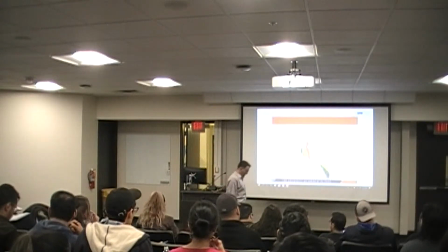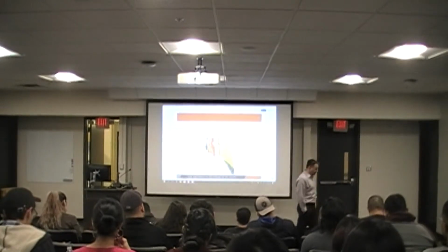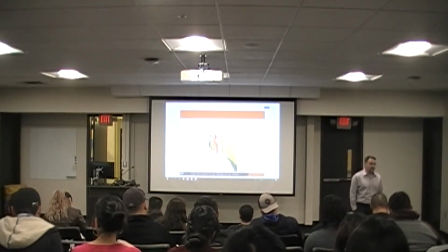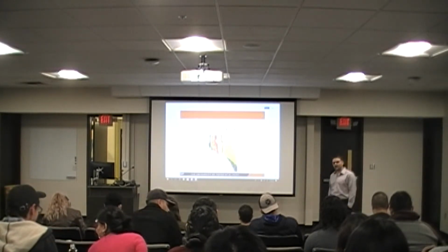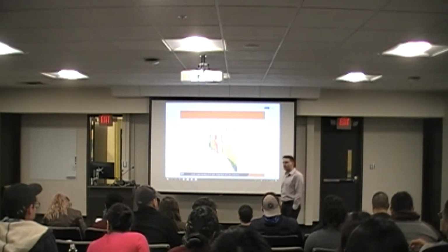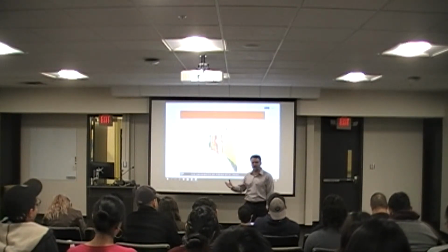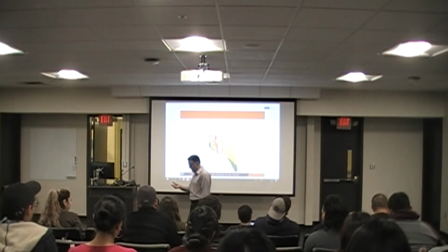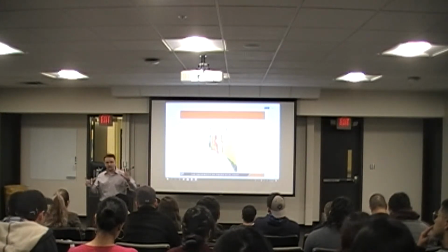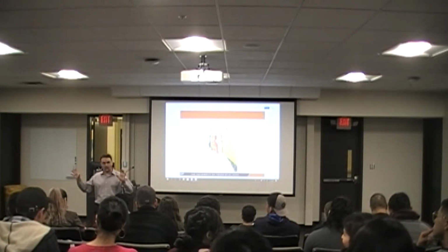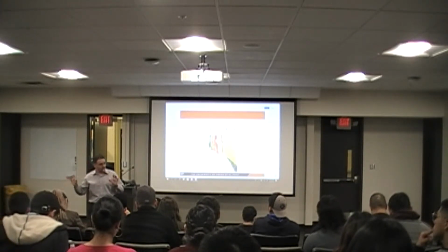In terms of the other designations that we have, for well-graded material, that would be W for well. And for poorly graded material, I will show that with P. So all of these are very intuitive. You know what the words are, and you can basically see the combination of the two. For instance, if I have G and W, the first one relates to particle size, and the second one relates to the gradation, right? The gradation distribution that we have.